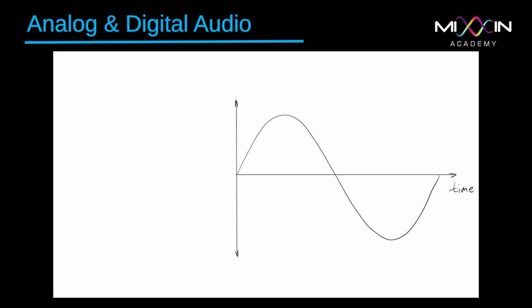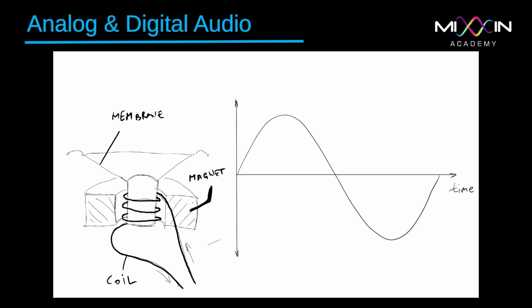I'm going to need this picture of a speaker membrane from a profile, cut out like this. What this is depicting is a speaker membrane, and the cone it has on its back end connected to it, with a coil running around it, and of course a magnet running around all of that. Once we run electricity through this coil, the electricity goes in through this wire, goes around the coil, and gets out through the other end of the wire. It produces a magnetic field that reacts with the magnet, pushing the membrane outwards.